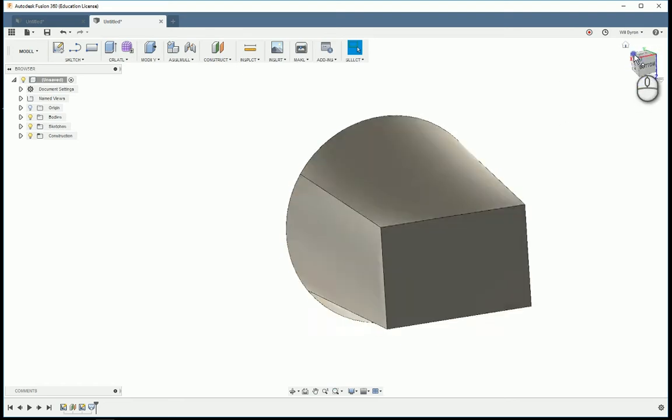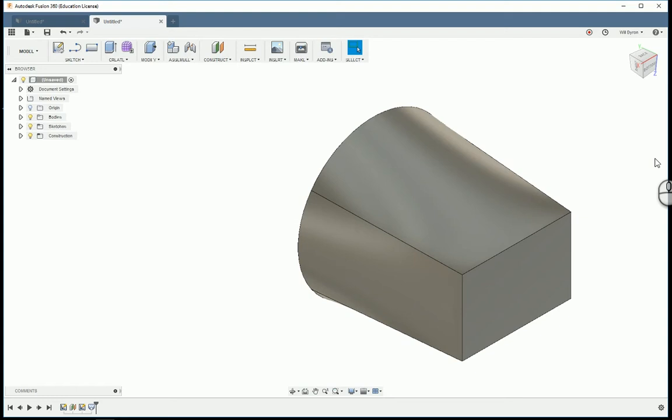Let's go to side view. This is what it looks like. Really, really nice if you need to do a friction fit. You can have a shape at the bottom, and generally taper it off to a circle. You press the 2 parts together, and it'll fit pretty nicely.